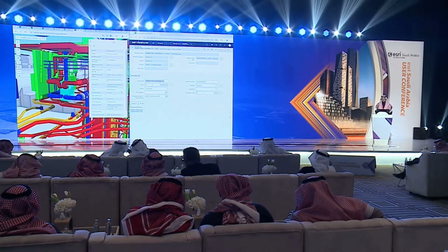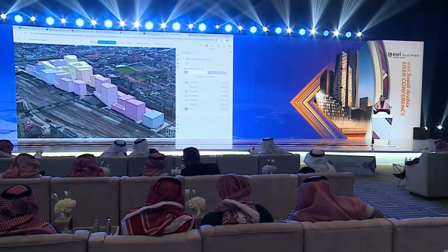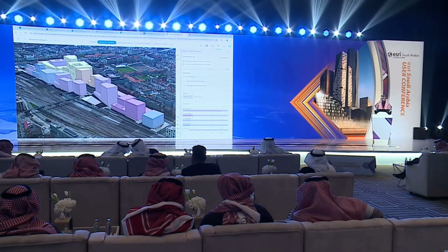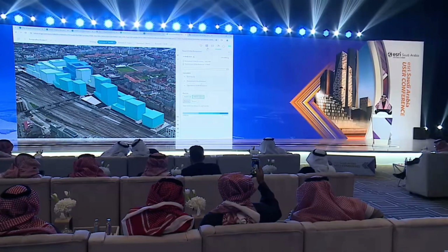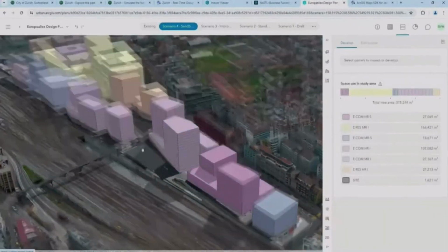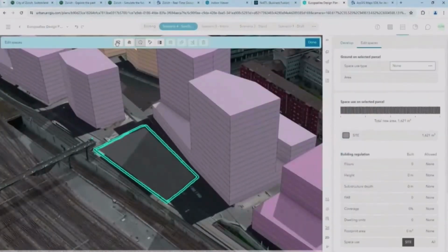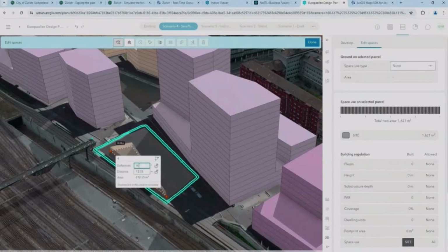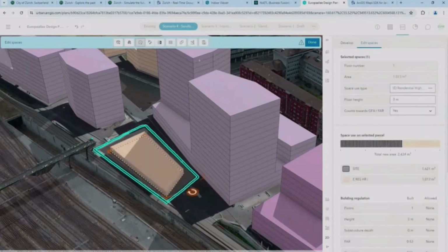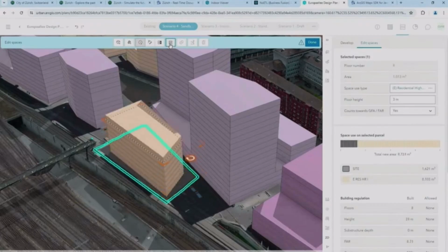Second, urban planners can leverage ArcGIS Urban to plan proposed developments in the city. This includes assessing potential carbon emissions associated with the design. Now new, the editing tools in ArcGIS Urban and the Scene Viewer allow users to set constraints. When a feature is added, such as a building, I can add a deflection angle of the next line segments and distances to the next point, greatly enhancing the editing experience.